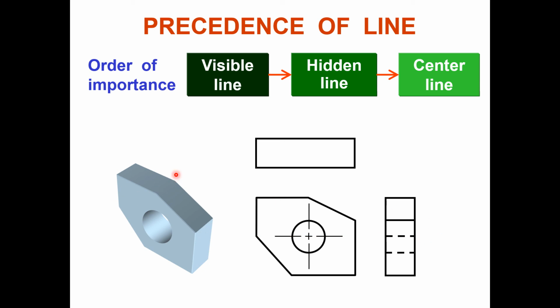Similarly, when we see from the top, hidden feature and show center line. Okay, again there is a cut, so the hidden feature will govern, that is acting at the same point, so no issue. Center line, but at the same point there is a cut, so we will remove the center line, instead we will draw a solid line. When you see from the top, there is a cut joining two surfaces, there will be an edge, so we write a solid line.